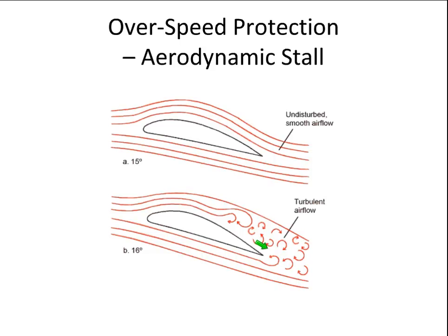And so that's a common way to reduce the rotation of those blades, by losing that energy. If we think about a large wind turbine, they can actually pitch their blades to either go through aerodynamic stall or just to lose efficiency to try to slow themselves down on an ongoing basis. Small wind turbines have to basically be designed so that at a specific wind speed this happens, or they have some type of passive pitch system that causes the pitch to change as the speed increases.